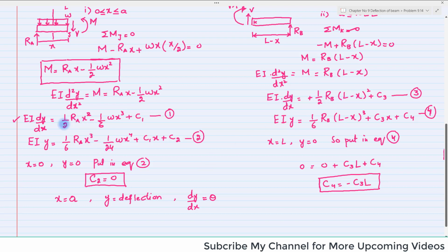So when you put x is equal to a in equation 1, it will be equal to 1 over 2 RA into a square minus 1 over 6 W a cube plus C1, and that will be equal to this term, which is equal to 1 over 2 RB into (L minus a) whole square plus C3.